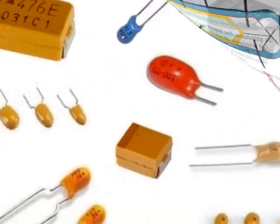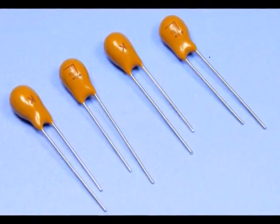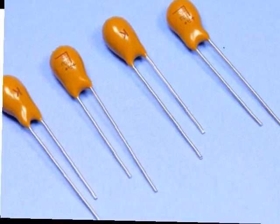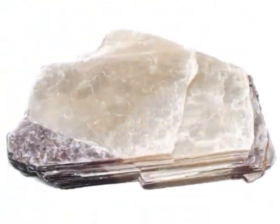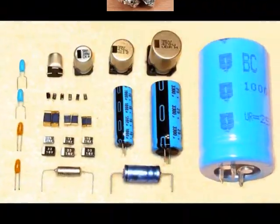However, these types of capacitors have relatively high leakage and low breakdown voltage. The metal plate of electrolytic capacitors is generally aluminum or tantalum. Tantalum-type capacitors are smaller than aluminum type and have less leakage and more stability than their aluminum type.